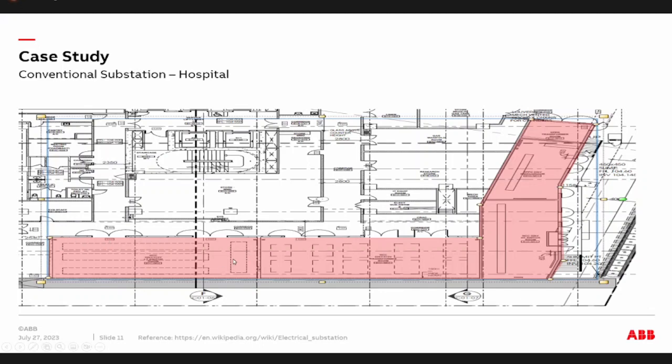So whether is it economical that we run low voltage cables from this location to the farthest point of the distribution, gaano na kalaki yung cables natin na yun. And of course, pag malalaki yung mga cables natin, lalaki din yung mga risers natin, lalaki yung mga other electrical rooms, no? Mag-house ng mga distribution cables natin. So we have to consider all those aspects.